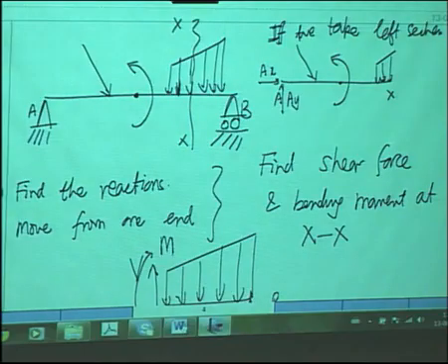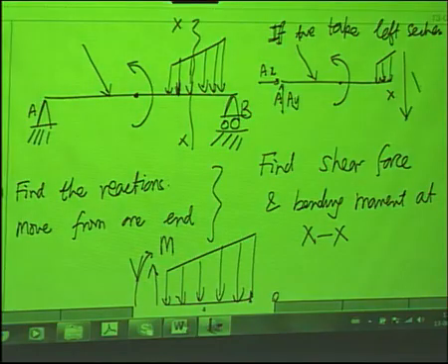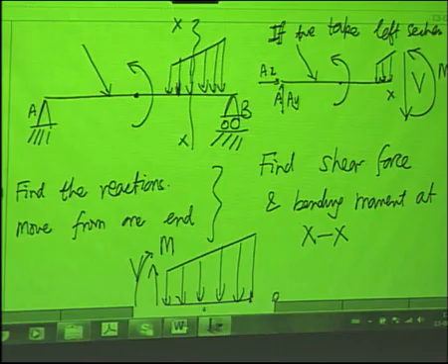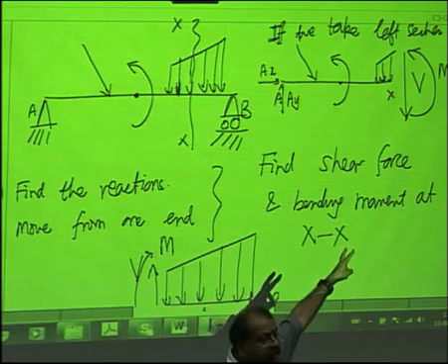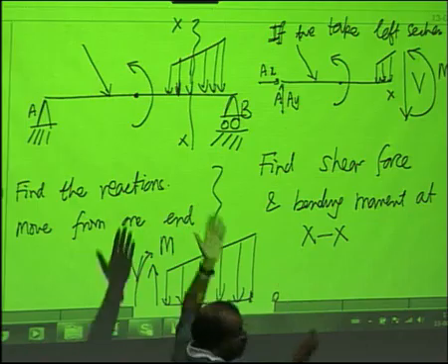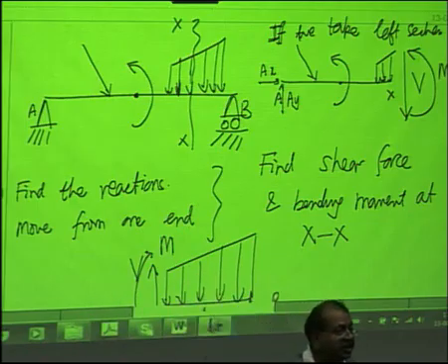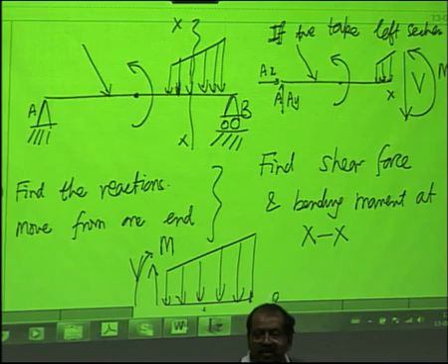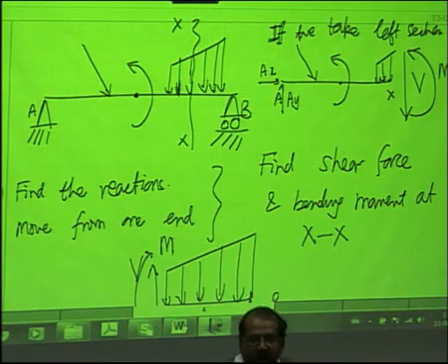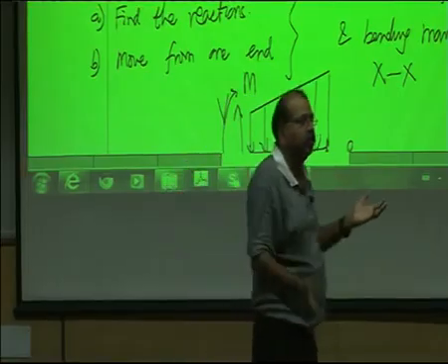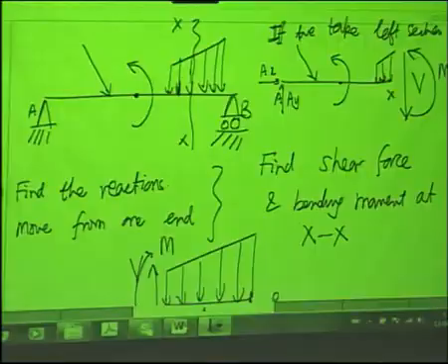But now the key would be, I would have shown V like this, and I would have shown moment like this, and once again if I do sigma fx is equal to 0, sigma fy is equal to 0, sum of moments is equal to 0, I will get V and M. And because the beam is balanced, whether I use the right section or the left section, I will get the same answers. And the sign convention ensures, because we have taken V and M and defined them in opposite directions, there will be no confusion. Hopefully this should clear your doubt.